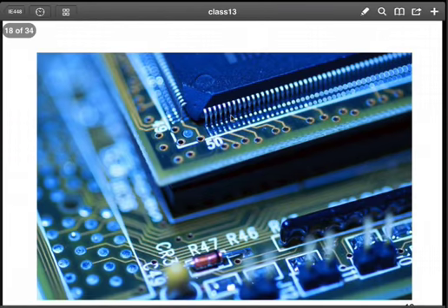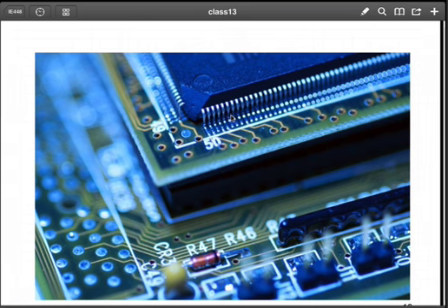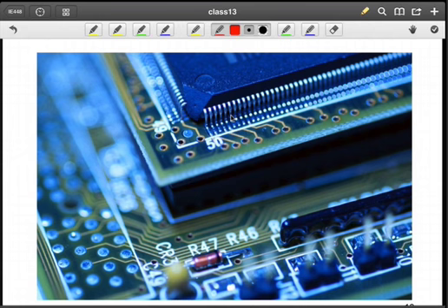Here we've got a circuit board with various components on here. The question is, what is the likelihood of performing rework? Well, it depends on the nature of the scrap. If the scrap has to do with the internals of the circuit board, in other words, we've got some bad layers in our pathways here, then that will be extremely problematic because it may involve going into layers of the circuit board that are not on the surface, and therefore that would be very difficult. R, in that case, would approach 0.